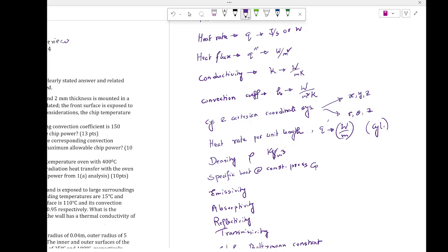Cp or Cv are usually used for gas. C is usually used for liquid or solid. Why? If the liquid is considered incompressible, the pressure doesn't have that much of an effect. Does it make sense? It does have different values though. That's the exception, okay? But for solid, definitely one value of C. P refers to constant pressure.